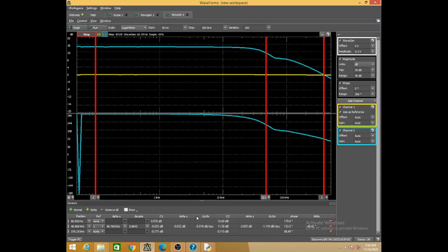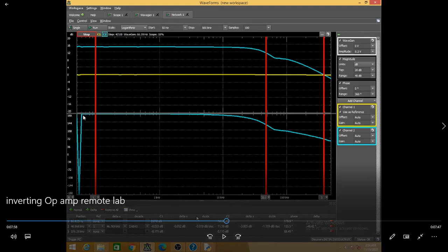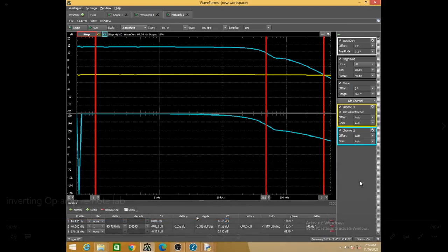So, do we now get to know whether some of the objectives are fulfilled? We could measure the DC gain. We could measure the 3 dB bandwidth. We could measure the unity gain bandwidth, and you can also verify the phase in the passband. Whenever it is DC gain, can you see the phase is minus 180 degrees or 180 degrees? Yes, sir. It's not minus; 180 degrees means it has a sign of minus.